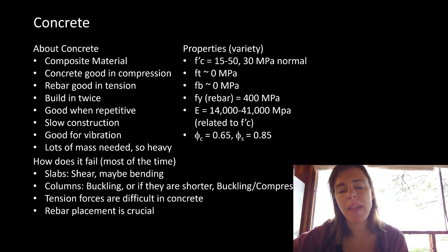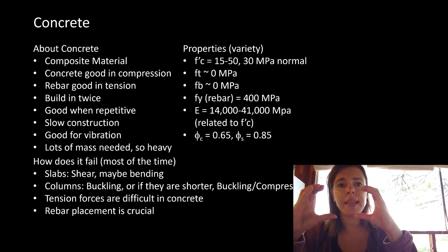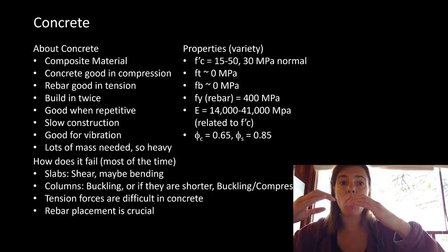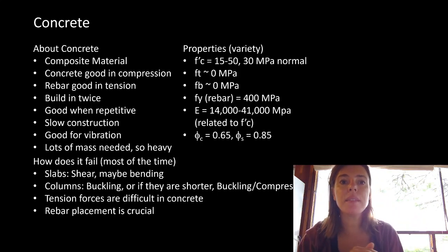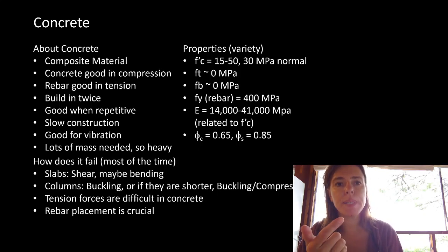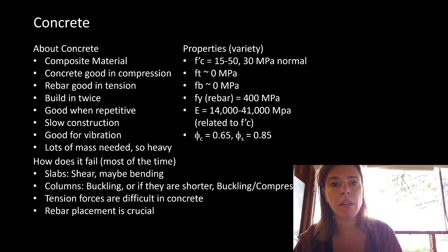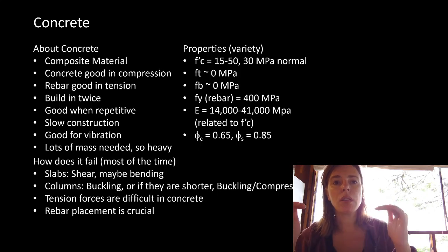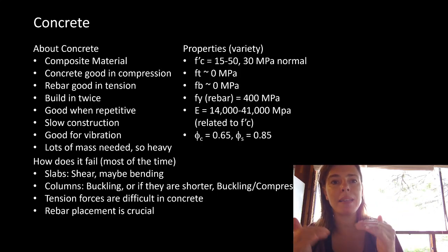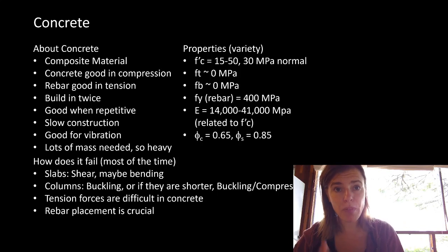Bending, we say the same thing, mostly because when it's in bending, one side is in compression and one side is in tension. So the steel does the tension work and the top side is actually in compression. So any time we need to talk about bending of the material for concrete, we're really talking about the top part, or wherever it's in bending, being in compression. So it's a bit of a rework there on how we talk about steel.